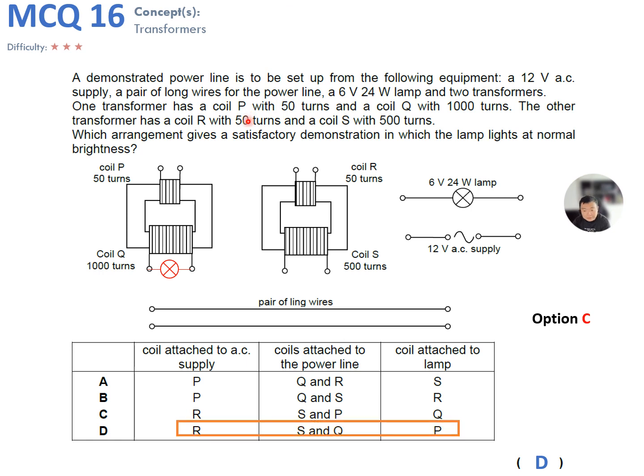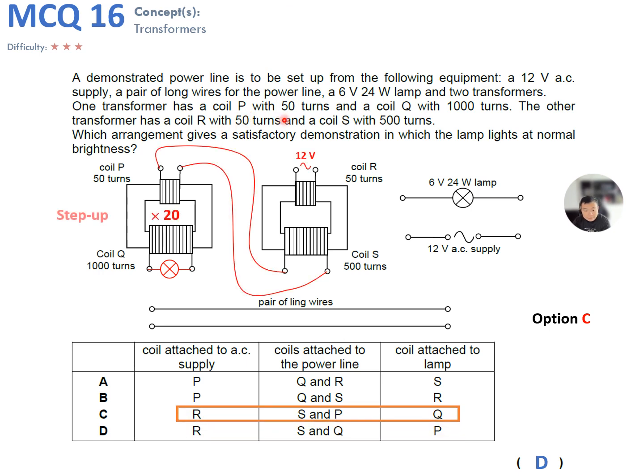And we go on to option C. This is the connection. So we will first step up the voltage from 12 volts by 10 times, and then we will step up again by 20 times. So stepping up twice, you should expect to get a very high voltage at the bulb. So 12 volts multiplied by 10, stepped up by 10 times, that's 120 volts. Step up further by 20, so multiply by a further 20, you get back again the same output voltage as option A. You will burn the bulb spectacularly again.